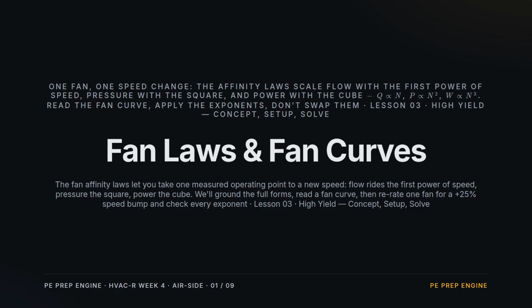Week 4, Lesson 3, Fan Laws and Fan Curves. The affinity laws are the airside workhorse. They take one fan at one measured operating point and predict a new one when you change the speed. Flow rides the first power of speed, pressure the square, and power the cube. We'll ground the full printed forms, read a fan curve, then re-rate a single fan for a 25% speed increase, and watch the one-place candidates lose the point, which is swapping those exponents.